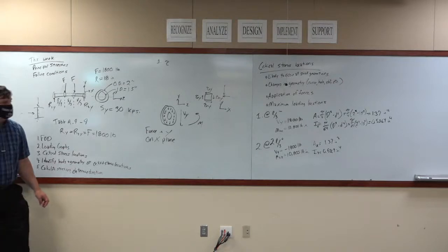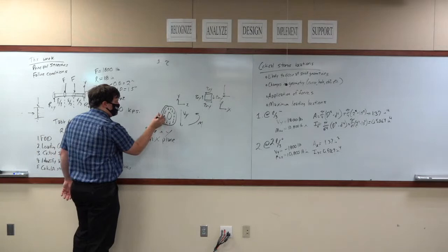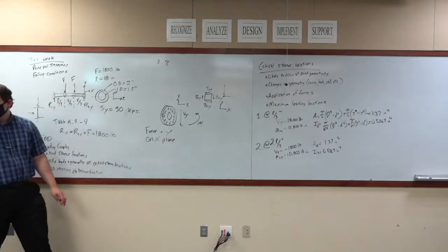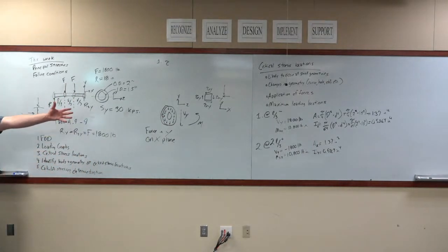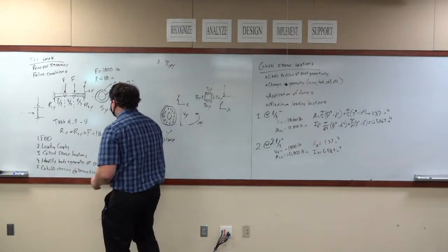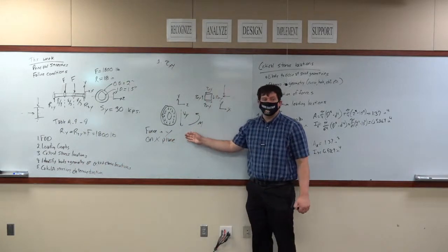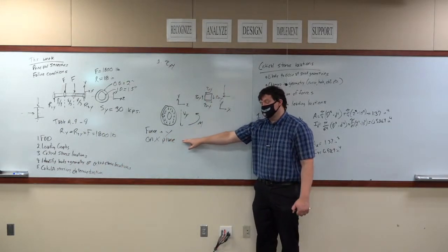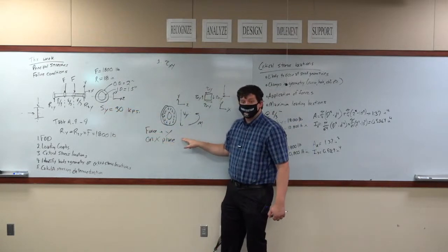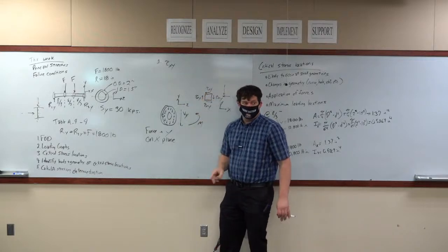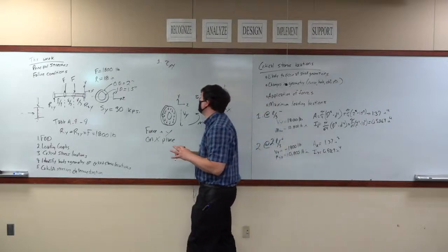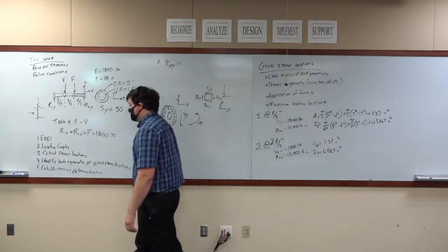Okay? And those stresses look like this, looking into the material. So that's a 3-dimensional view. Okay, so we have tau xy's now. The easiest way to figure that out is just by knowing the force is in the Y direction and it has to be carried along the X plane. This is the X plane, carrying the force in the Y direction, therefore this is a tau xy. Yes, there are engineers who still struggle with figuring out what shear stresses go where. That's why I'm trying to help you there.